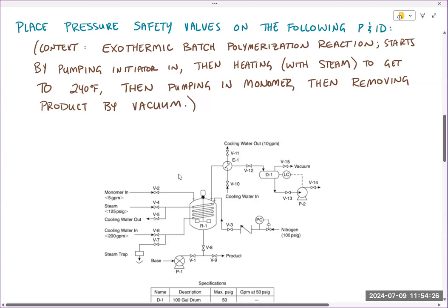So you can see why I had this video on how to read a piping and instrumentation diagram, because it could be a little bit confusing, at least at first, to figure out what's going on. Oh, this LC, remember, is a level controller. So it's going to read how high the liquid level is. And then presumably it's connected to this pump by an electrical signal. Once the level gets to be a certain height, it's going to tell this pump, hey, you have to turn on, because that's going to drain the liquid out of this drum D1.